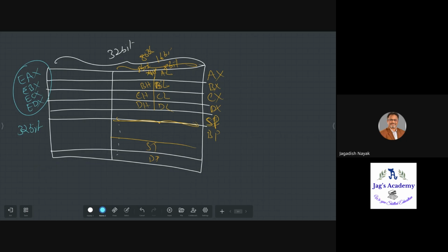In such cases, you have to mention in the assembly or machine instruction, by using some prefixes, that you are using the 16-bit mode of operation but with 32-bit registers. I will tell you that. Suppose you are using the 32-bit mode of operation and you have 16-bit registers in it. Then once again there is something called a violation, and in such cases also you have to tell the microprocessor by giving some prefixes. I will explain by solving one question where to put the prefixes and where not to. Remember this. This is very important.